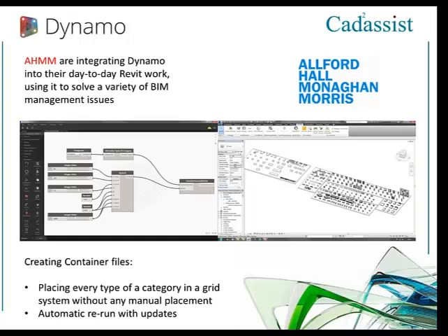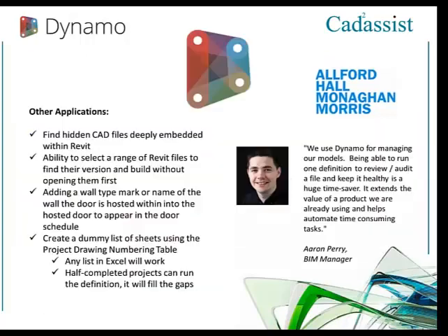So if you want to build in a rule that for every desk in a floor plan there will be a bin, for every 20 desks there'll be a photocopier, and so on, all those rules can be built into your Revit model, saving time.